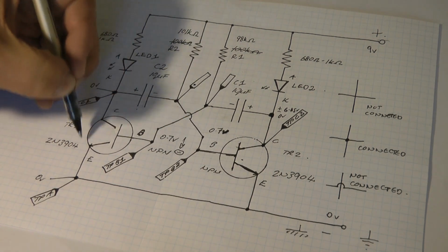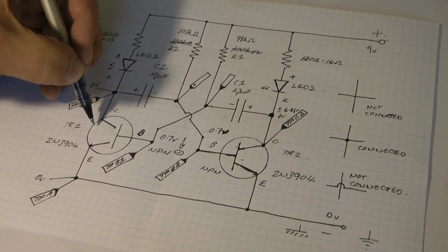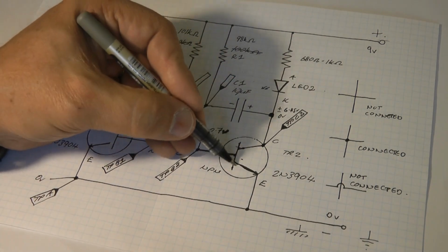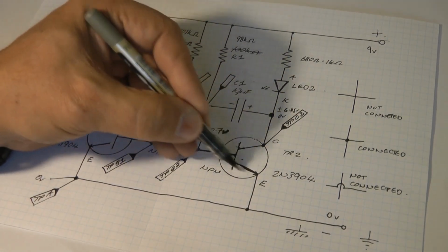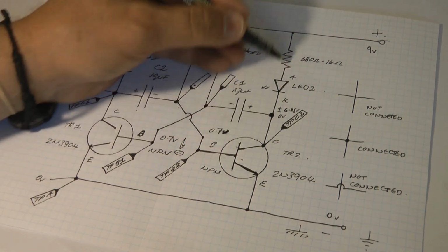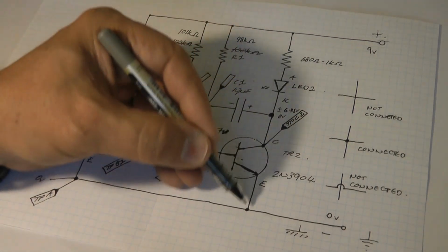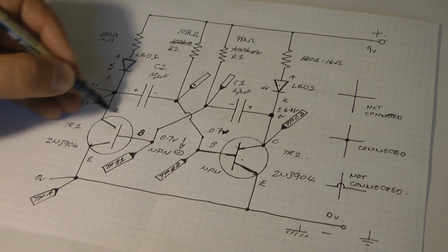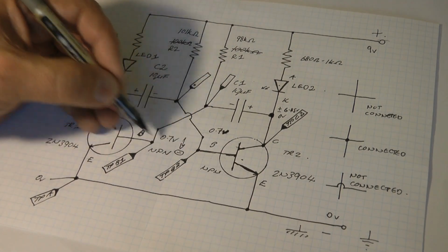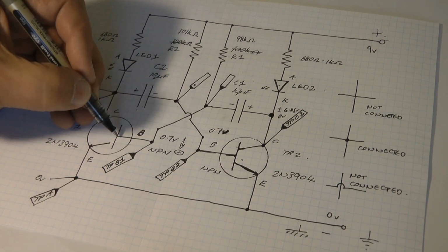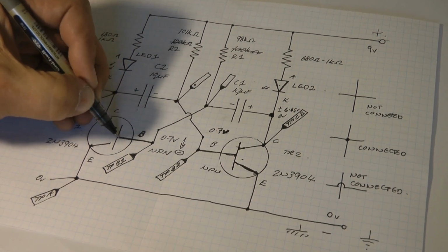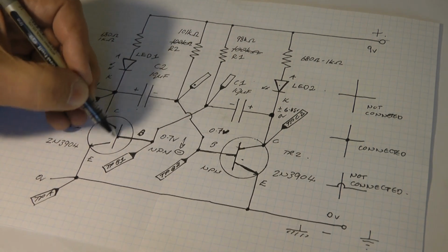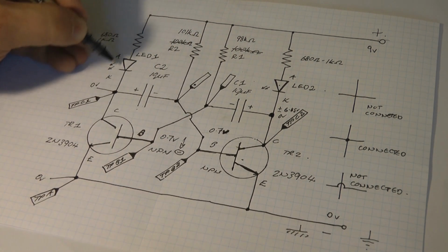Now this transistor is in an off state, and what we need to remember to mention is that the moment this transistor is a closed contact or an on switch, current can flow through this path and the LED lights up. So when this transistor has been forced down into negative territory and it's no more biased forward, so we don't have the bias voltage here to switch it on, this LED is off.